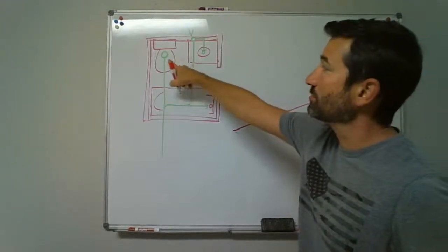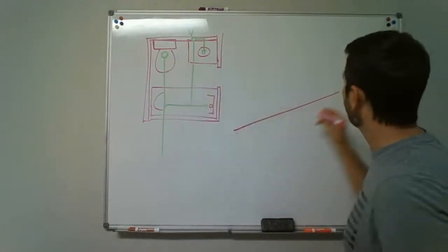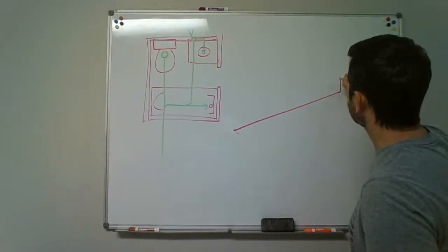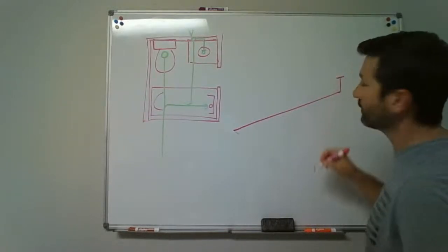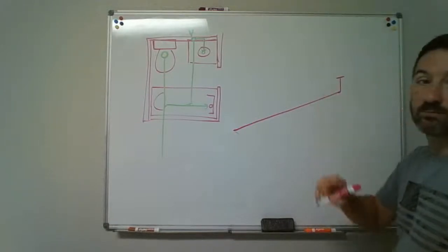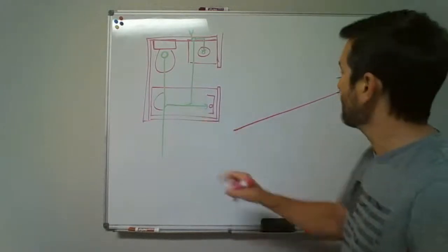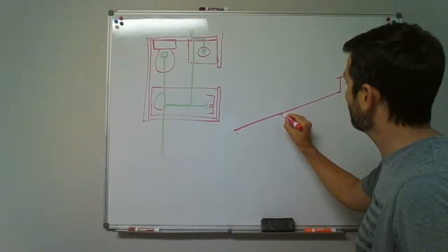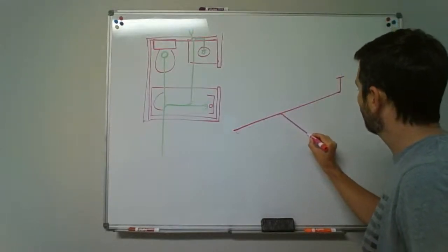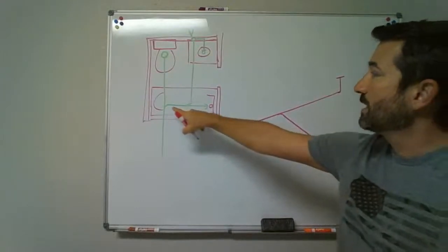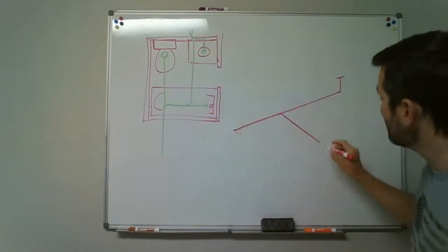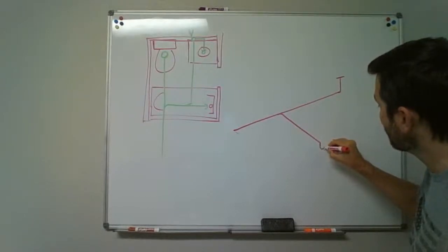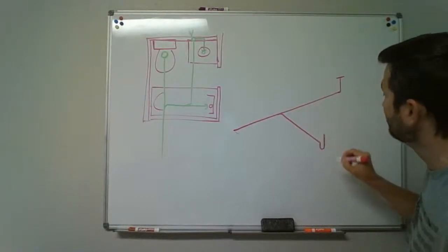Now circles on a bird's eye are going to be vertical pipes, which on the isometric is turning straight up. There, we've got a toilet flange sitting up on top of it. So we just plumbed up our toilet. We come down here and make this connection. So that's going to come off about like this, kicking across this way. We came straight across. It ends up with a P-trap for this tub. So a P-trap is straight down, a dip, and then straight back up.